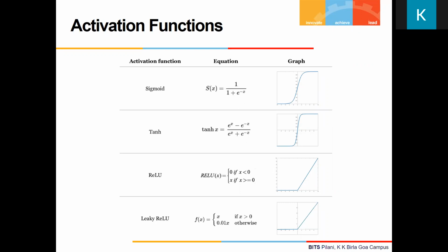So weights require n bits, input requires m bits. Multiplication will require n times m bit width. And if I am adding it 100 times, each addition may require one additional bit. We have the theory. I can find out how many bits I need in the worst case. That's how I get the worst case.